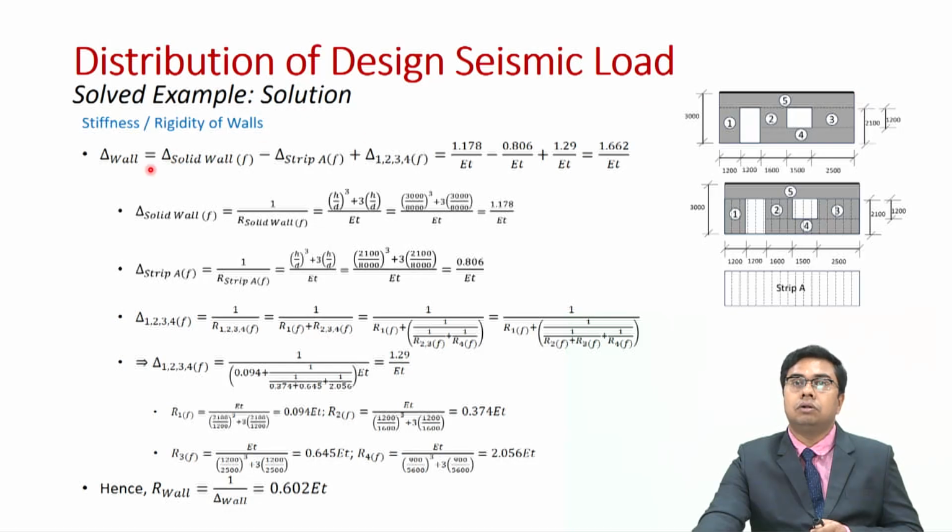Obviously in our case also this is a fixed wall, because of the presence of the RC slab spanning over the wall completely. So the first thing we have assumed is a solid wall, so we have ignored these openings.